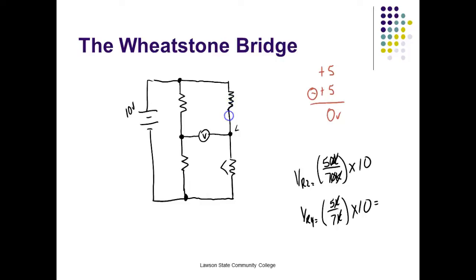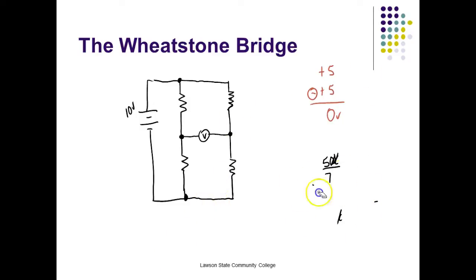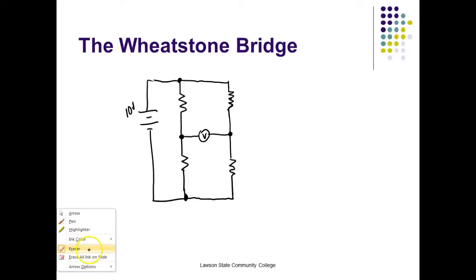And you're going to run into the Wheatstone bridge all over the place because of sensors that vary their resistance with what they measure. So I'm going to put my thermistor on the bottom just because it's easier. So I've got my thermistor over here, right? And it varies its resistance with temperature.